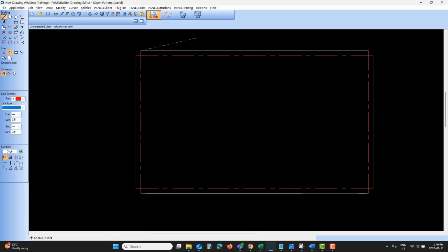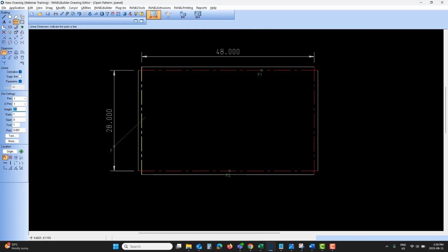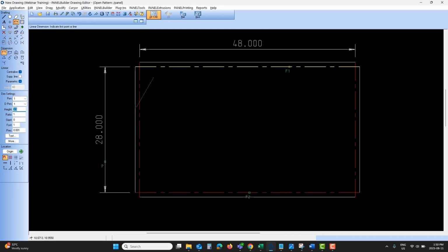Okay, now that we have our bend lines added, we need to dimension out the shape. Because as mentioned, with it being parametric, these need to be identified for redimensioning or anything of the sorts. So we can see here, we have these dimensions locked in and everything seems to be green. We're going to go through, dimension out our bends here.